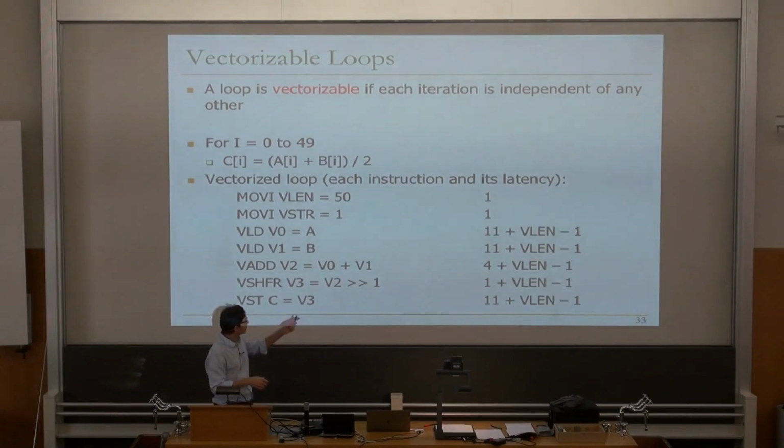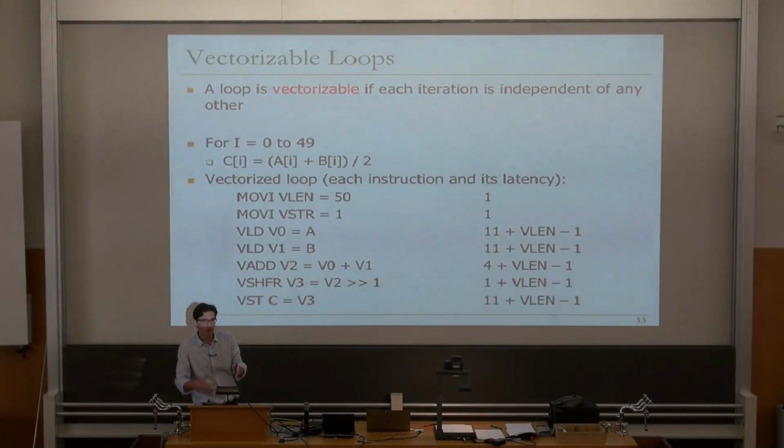So in the case of the vector add, you will see the 4 cycles for the first element, and because right after the first add started, you can issue the next add for the next element. As soon as these 4 cycles finish and you get the first result, you will only need 1 cycle more to get the next result, and then the next result, etc.